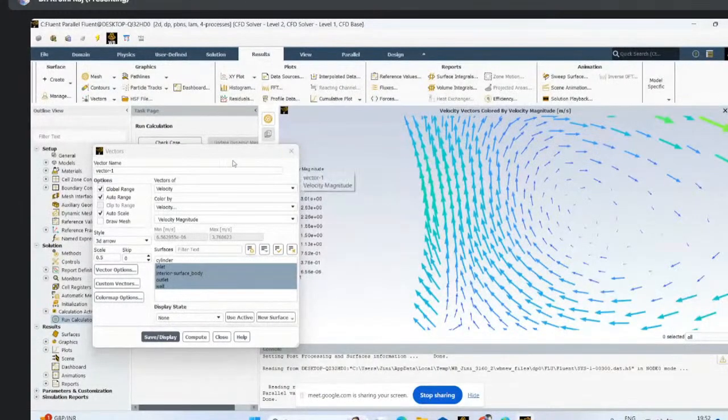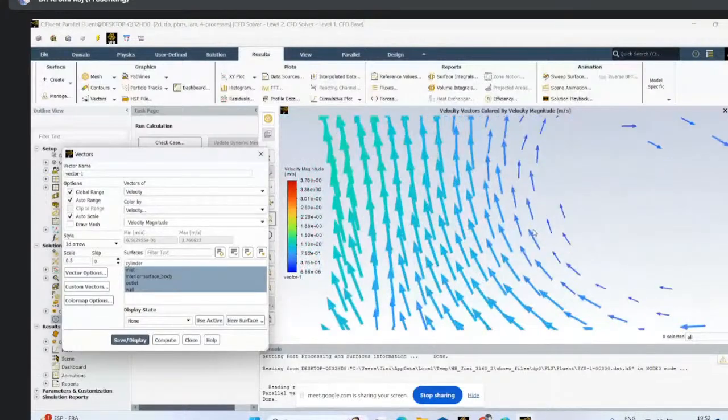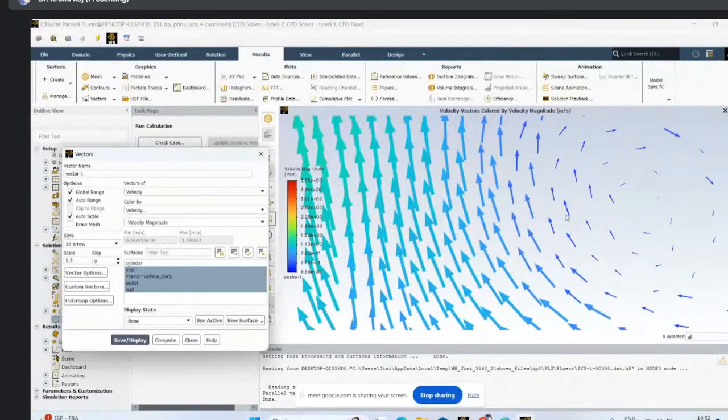That I will show, if for some cases we can run, and we can take it for the work which you guys will do. In that case, we can take all the things. So how the vectors are rotating, in that way only the streamlines will be. If there is a vector rotation, you can straight away say there is a recirculation region on either side of the cylinder.